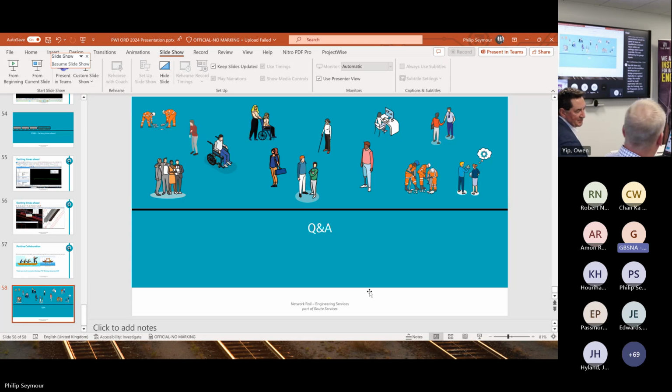Did we actually do any changes on that? I'm sure we did. We may have done, but you can set the chainage that will link, and how you display it is up to you, because we can turn on in that profile view the cardinal points, straight to curve, curve to spiral. Turn those off and just have 10, 20, 30, 40 if you want. That's just a view option. The geometry underneath is still doing its same stuff.